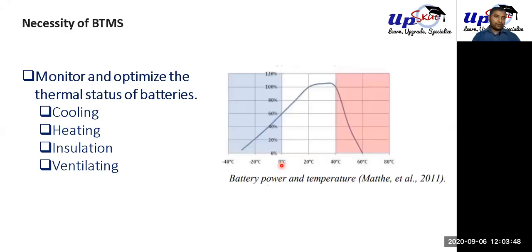Insulation is also very important, especially in cold countries. In very hot countries also, like when you stop your car over a tarmac, a hot beach road, instantly it soaks up lots of heat from the road itself. Then having an insulation mechanism prevents that, right? And in colder climates it's very crucial. You can heat up the battery a little bit, not while charging but while discharging or in running condition. A little bit of heat is acceptable, but if the cold is high then you will definitely lose your battery capacity over time.